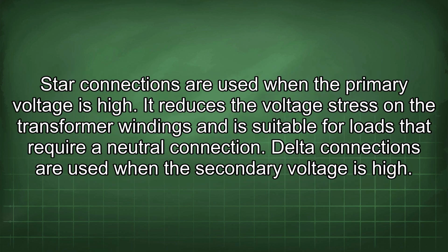Star connections are used when the primary voltage is high. It reduces the voltage stress in the transformer windings and is suitable for loads that require a neutral connection.